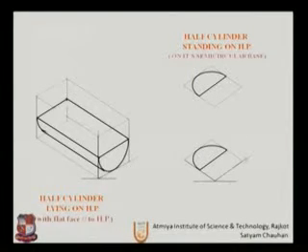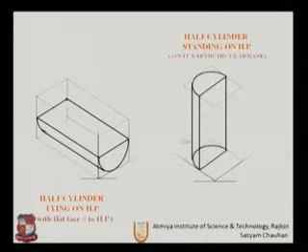So first, to draw the top and bottom of that cylinder, draw the bottom, the base rhombus, and the top rhombus. So we have a top and a bottom. Simply draw the outer line. So which line will not be visible? It will be this line. So simply delete that line, as we can see only this face.